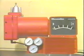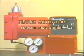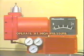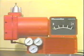One type of actuator that has been developed to overcome these limitations is the piston actuator. A piston actuator can easily be designed to provide a long stroke and to operate at high pressures. Because piston actuators can operate at higher pressures than diaphragm actuators, they can deliver more force to the valve stem and plug. Since a controlled air signal is typically only 3 to 15 psig, positioners are used in conjunction with piston actuators to provide air at higher pressure to the piston.